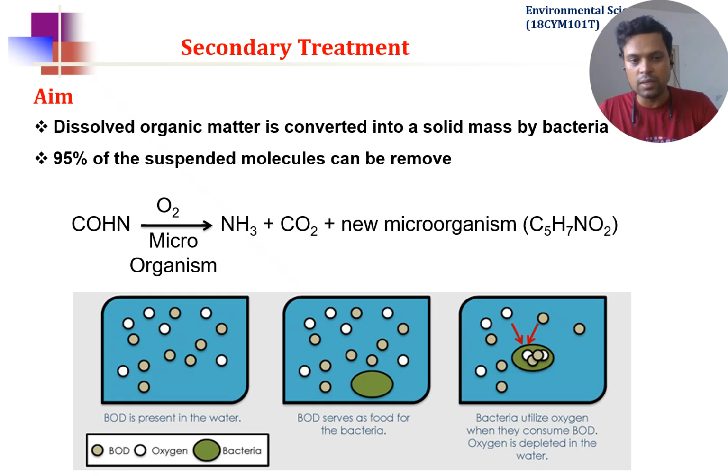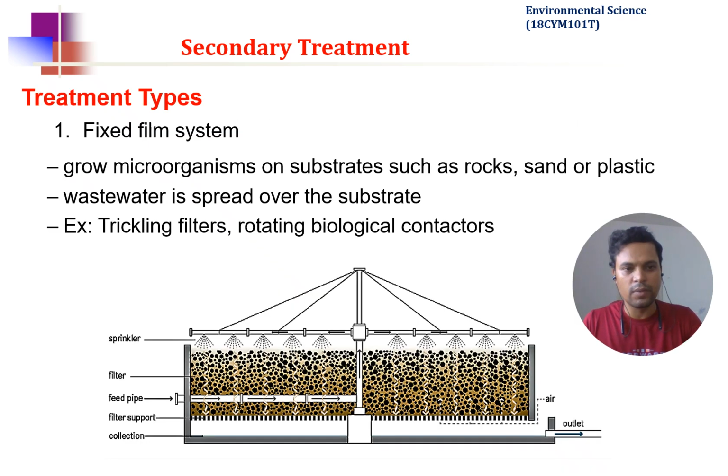which is basically the organic compounds. And then we have bacteria which will digest all these organic molecules in the presence of oxygen, and then they will divide and produce more and more bacterial cells. Okay, and slowly all these organic molecules present in the wastewater and the oxygen will be consumed. So this is a very important step in the wastewater treatment plant. I will discuss a little bit more on this.